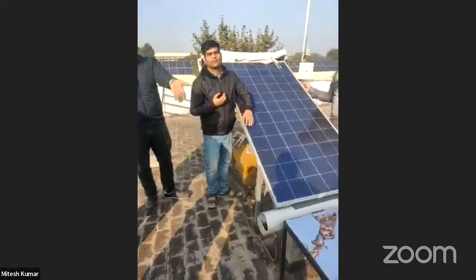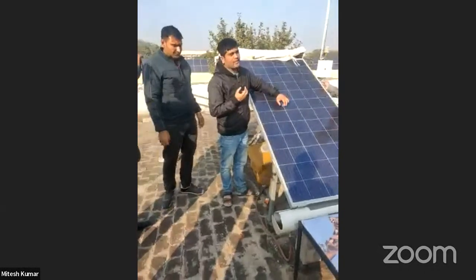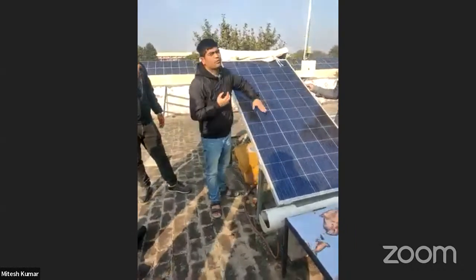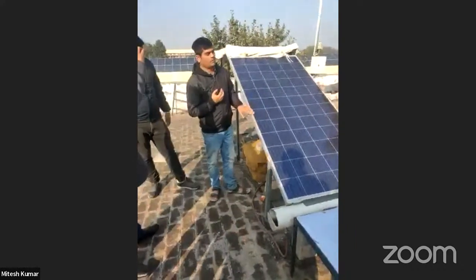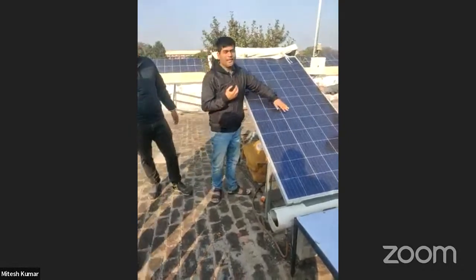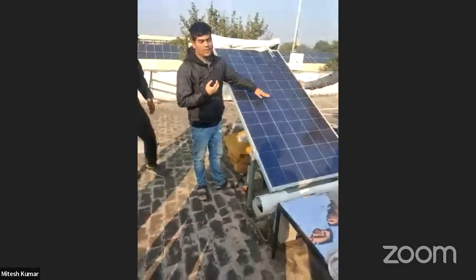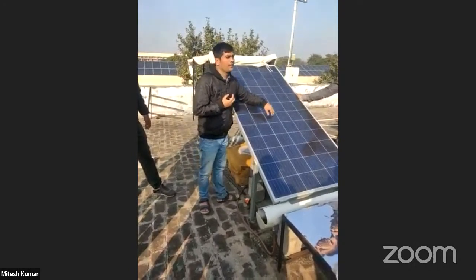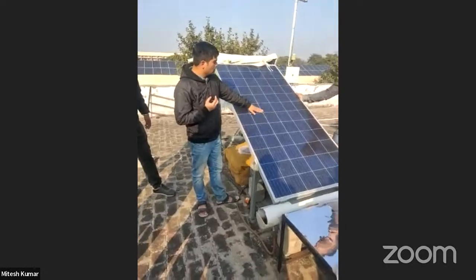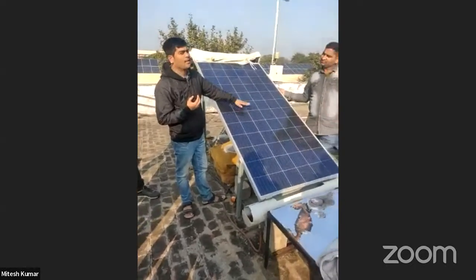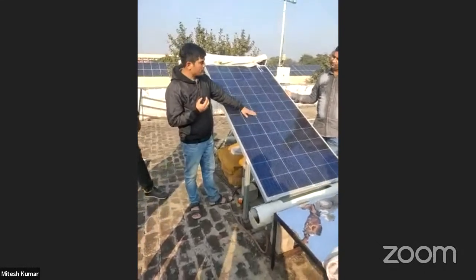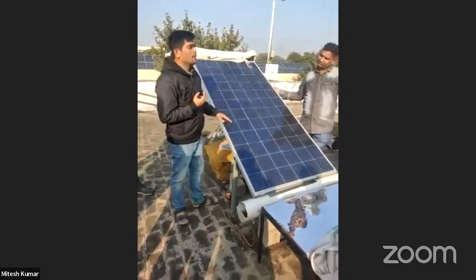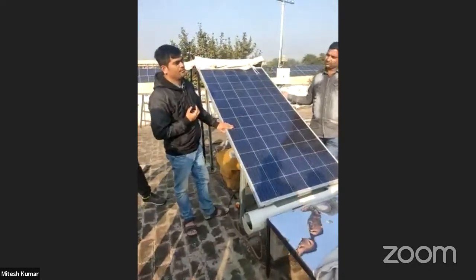Some angles, and we rotate at those angles. Actually, the power density decreases as the temperature rises. So there is a cooling purpose for the entire system, so that the temperature is maintained within the limit. To limit the temperature, we can raise the efficiency of the system. We have to maintain it below 50 degrees centigrade for a PV collector. By circulating fluids like water, air, etc., we can raise the efficiency of the overall system. The basic purpose of cooling is to maintain the temperature limit of the system.